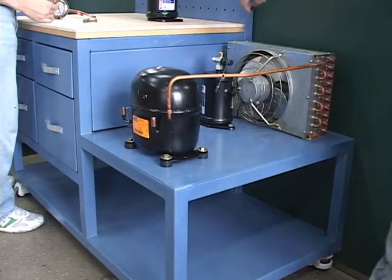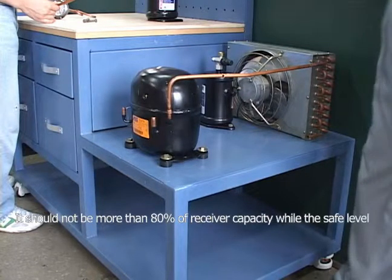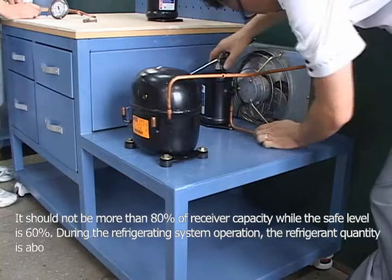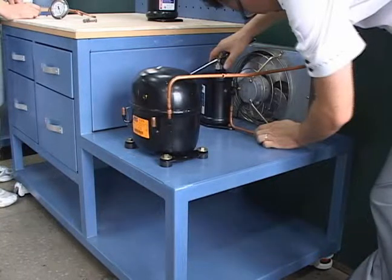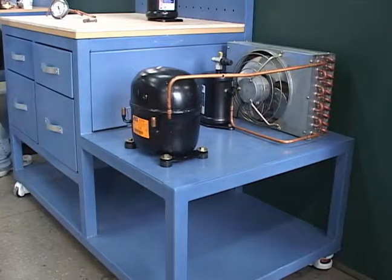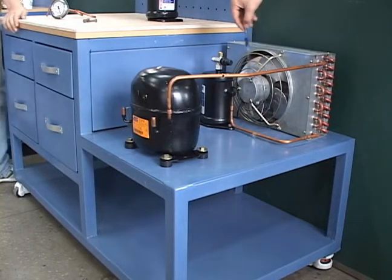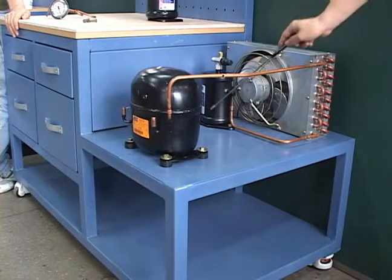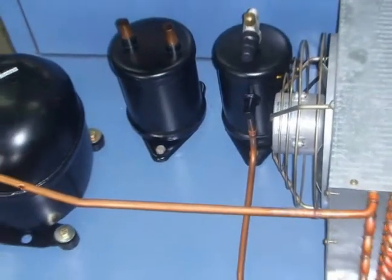When the whole quantity of refrigerant in the refrigerating system is stored, it should not be more than 80% of receiver capacity, while the safe level is 60%. During the refrigerating system operation, the refrigerant capacity is about 20%. In a large refrigerating system, a pressure purge is installed to prevent the pressure increase in the receiver, which can be caused by gas generation by heat from outside, when the whole quantity of refrigerant is stored in the receiver. This refrigerating system is a small one, therefore there is no pressure purge. When the receiver has been fixed, the piping at condenser discharge and receiver charge will be completed.